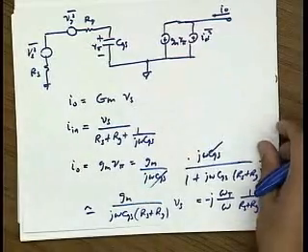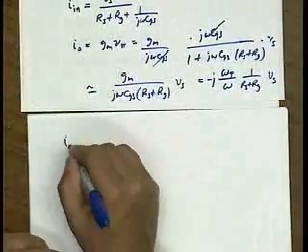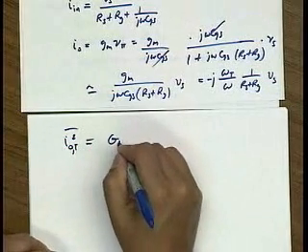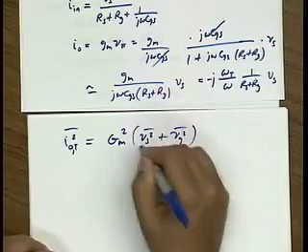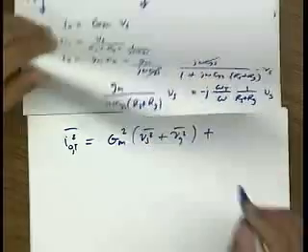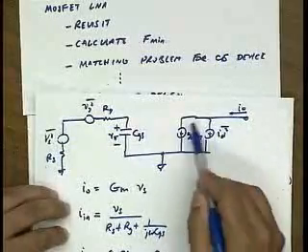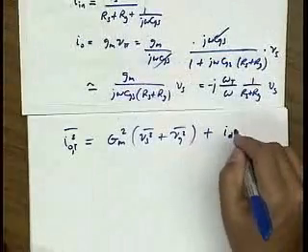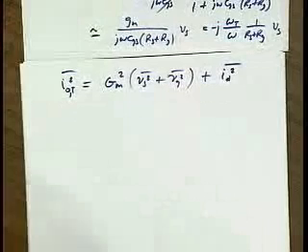And in fact, you can see that it allows us to very quickly calculate the total output noise. Total output noise, therefore, is just Gm squared times Vs plus Vgate plus, if I go back and look here, total output noise is this drain noise plus the current gain, which we've already included. And so this is the drain noise squared. Okay. Any questions?